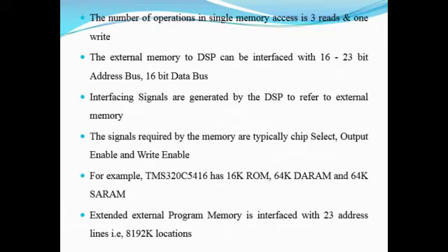The extended external program memory is interfaced with 23 address lines, making it 8192 kilo locations.